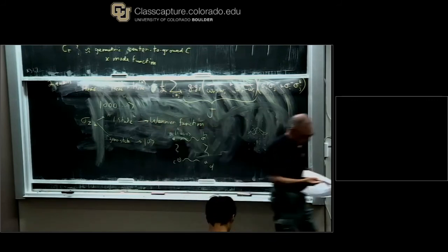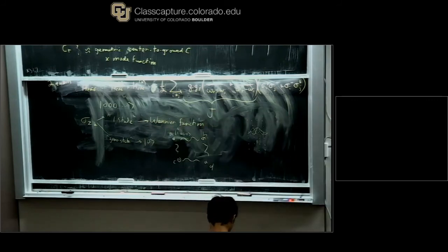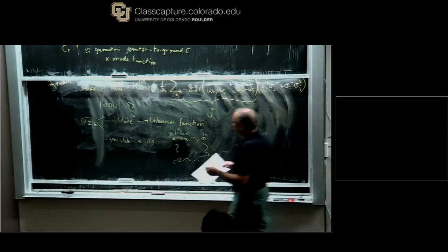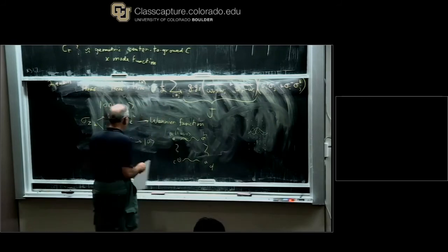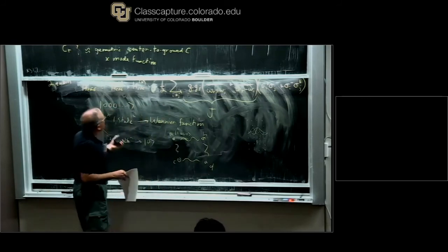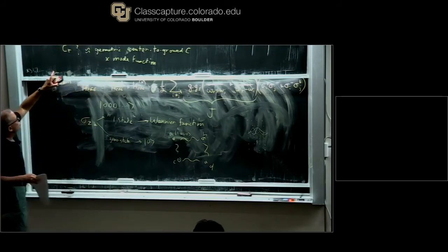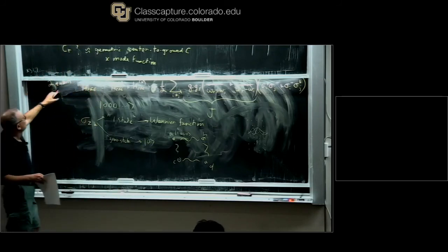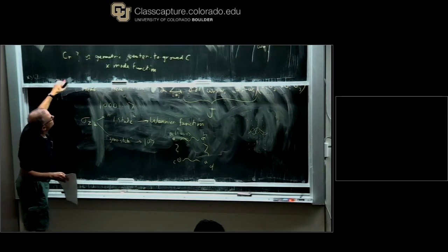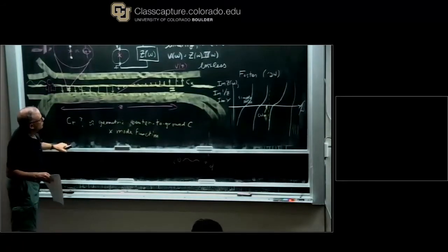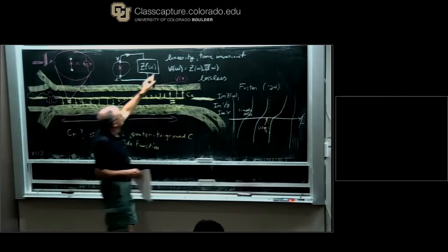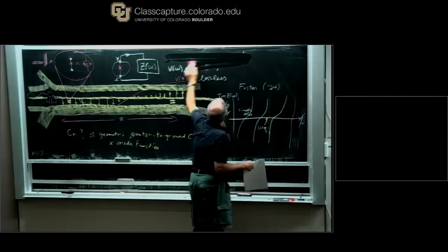Okay, so I promised that there was still something radically missing in circuit theory. Let me get into that, the word being reciprocity or non-reciprocity. Let me get into that by saying that one thing that's useful to know is that there is a black box model, and there is a Foster theorem, although it's called Cauer's theorem, for the many junction case.